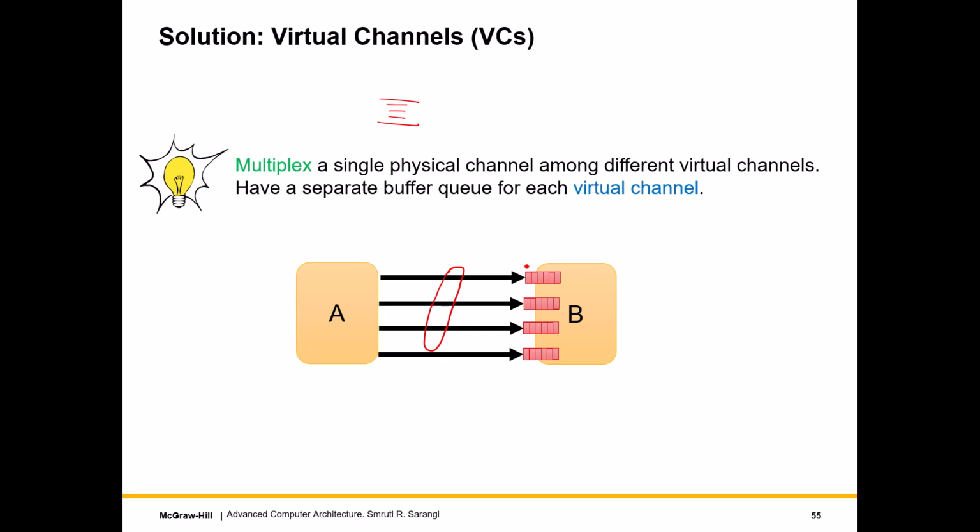In this case, the destination is B, and even though all the virtual channels are sharing the same physical channel, the same copper wires, logically it is as if there are 4 separate channels and 4 separate flows on the channels, and each channel is associated with its own set of flit buffers. This is nothing different from a busy intersection of roads.